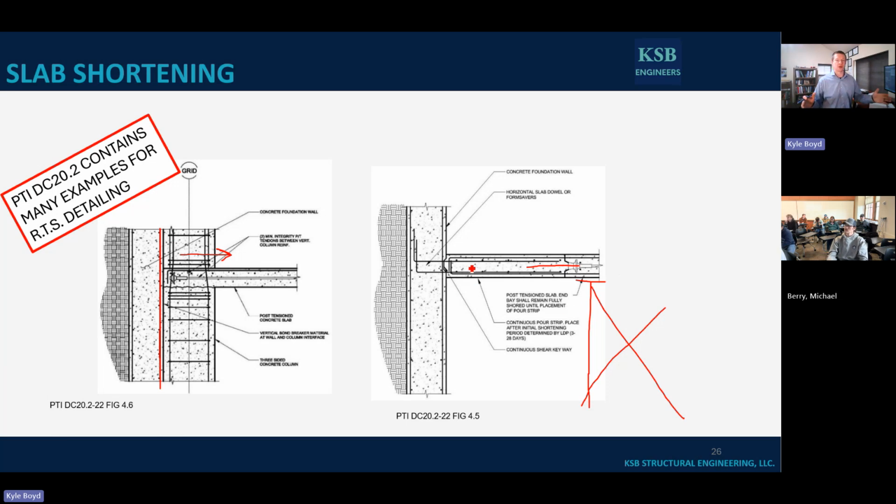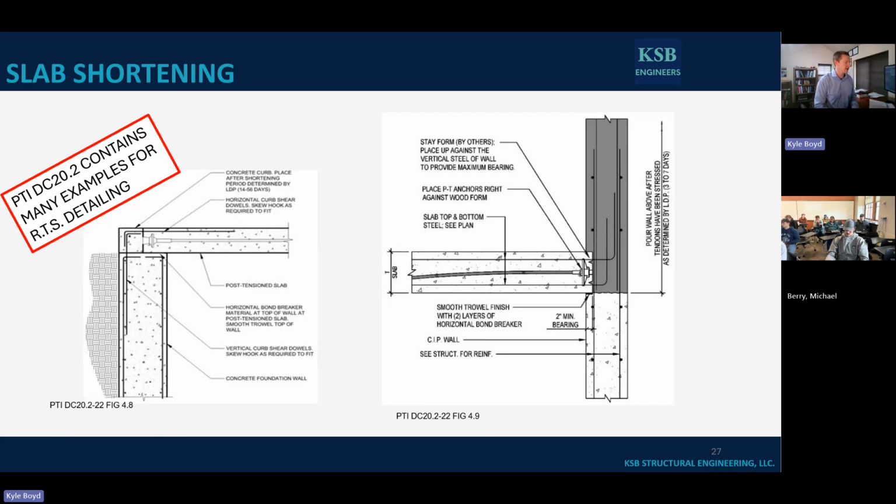Now I'm hard tied in though, so I better be damn sure that whatever movement, once I tie that thing in, I have enough rebar in there to prevent those cracks. What I'll do on a subterranean garage like this is I'll just put in a very light mat of number 4s at 24-36 bottom, just to help with some of that crack control, because I know long term I'm still going to get that, and I'm fully restrained all the way around the perimeter on there.